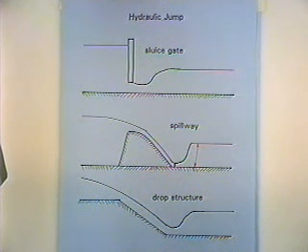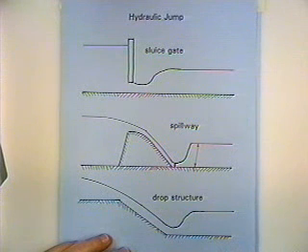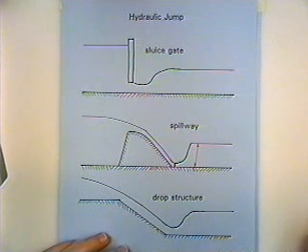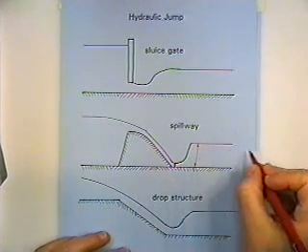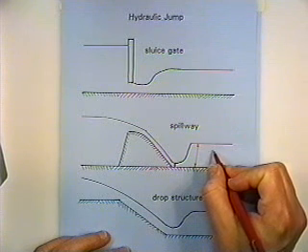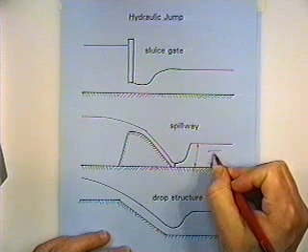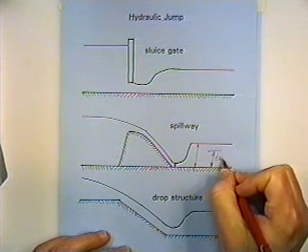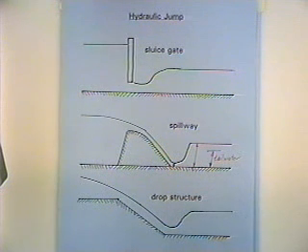Then let's say we went back to the water surface profile computations, and we started downstream here someplace, did backwater computations using the energy equation, the standard step method solution of the energy equation, and we worked our way up and we computed a depth. Let's say we computed a depth right here. And engineers would call that the tailwater depth. Uh-oh, so what's wrong? I did two sets of computations.